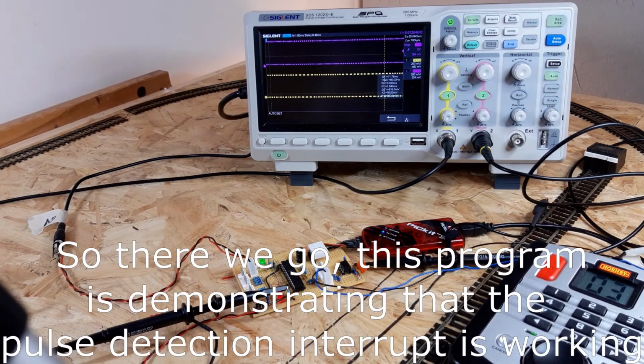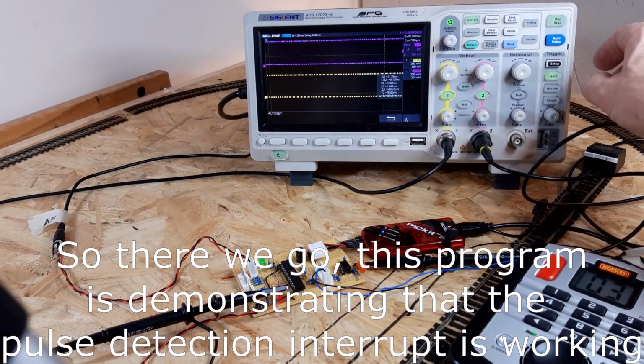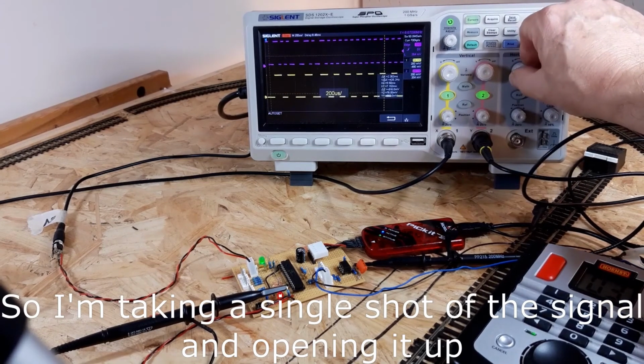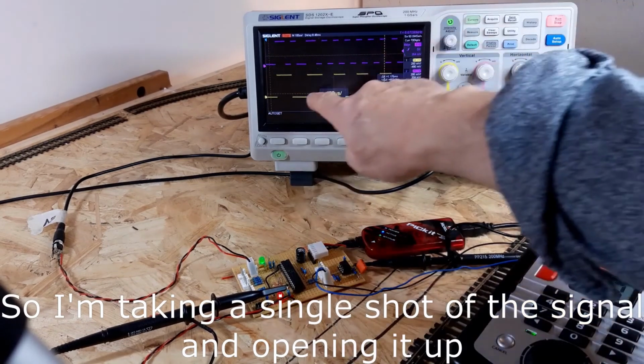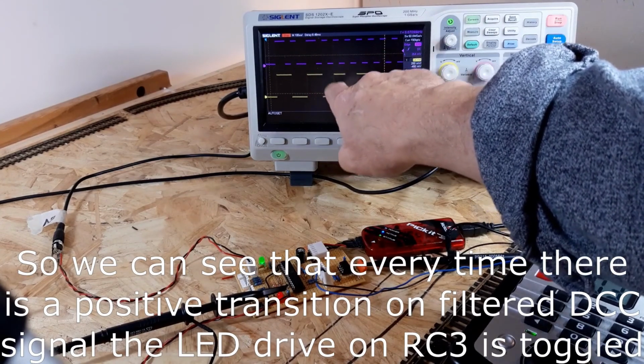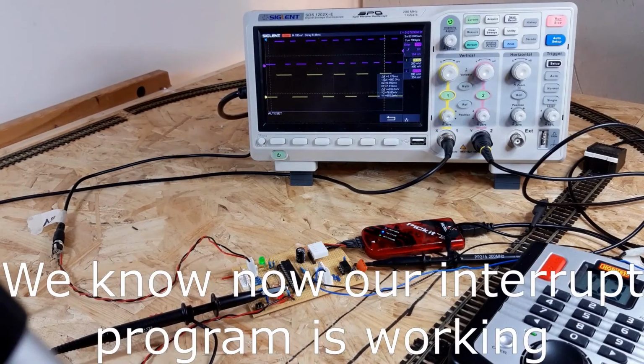All this is demonstrating that we've actually got an interrupt happening on the pulse width. So I'm going to single shot it and open it up. And what we get is every time there is a positive transition, the LED is toggled. So we know now that our interrupt program's working.